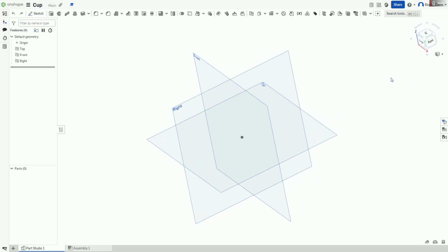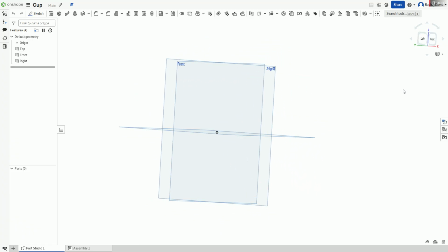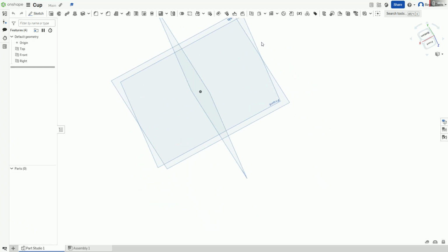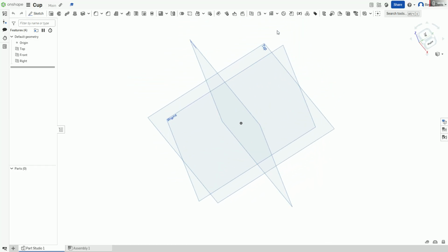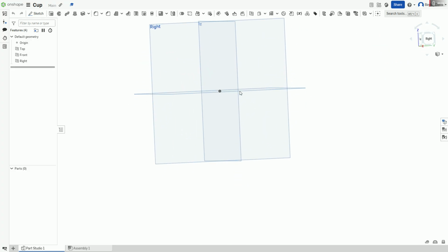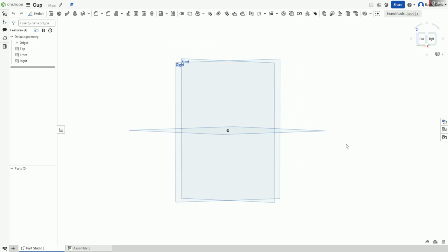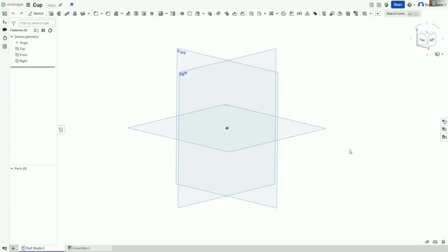Now, at the top right of the document, you will find a cube. That shows you where exactly on the model you're facing. You can use right click to spin around and middle mouse button to shift yourself side to side or up and down. For those that don't know, the middle mouse button is when you press the scroll wheel down and it feels like a button. It's like taking a controller and pushing down the joystick. Exactly like that, but with a mouse. Now, if you don't have a mouse, I wish you the best of luck.